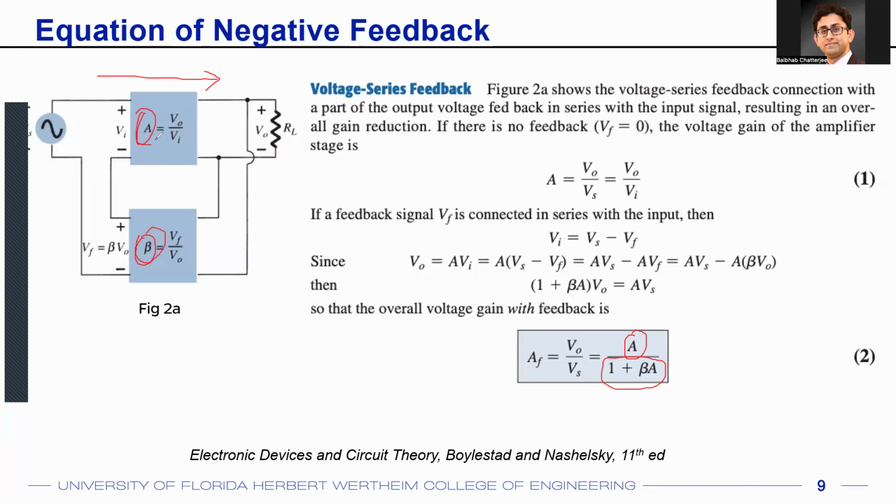On the other hand, stabilizing the gain A is not very trivial. All of you bought these op amps for your labs, and you might see that in the open loop condition, everyone's gain of that op amp will be very different. And it may not be only 5 or 10%, it could be 20, 30% in certain scenarios.